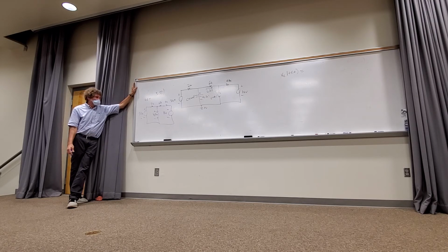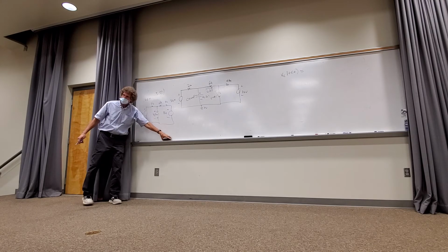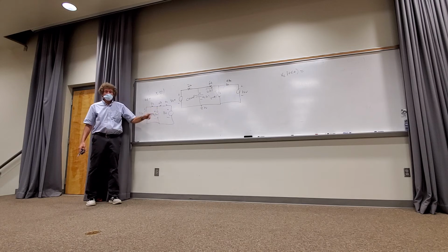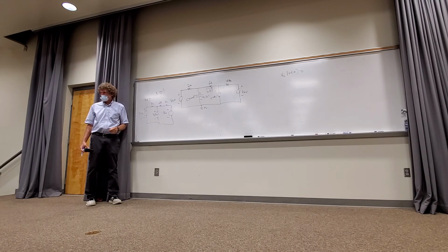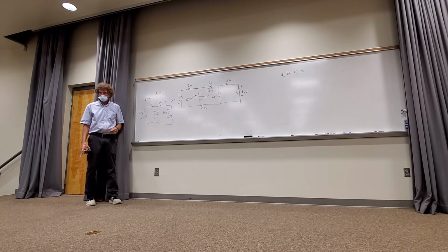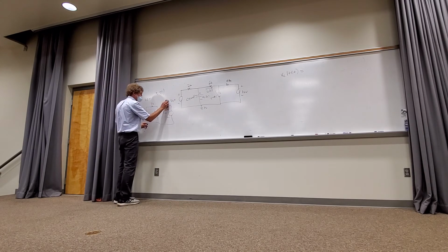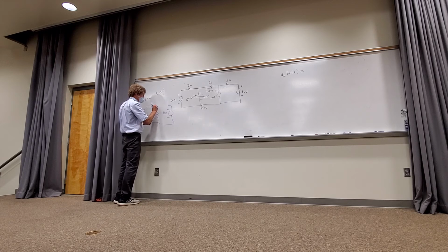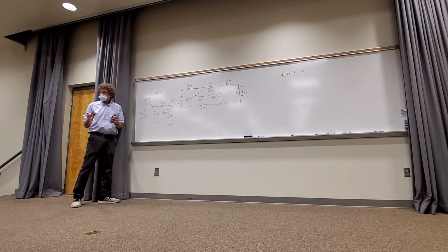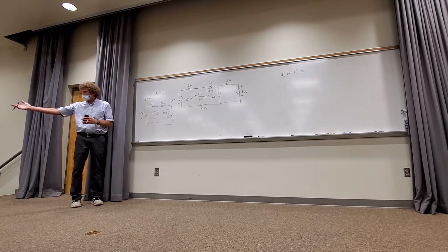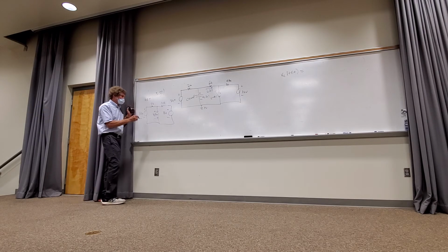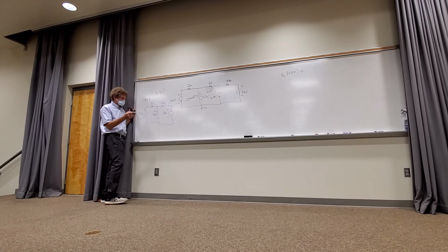All right, now I want this voltage. How you do it at this point is up to you. I would make one suggestion. This right here looks like a single resistor to me. You agree with that? So I'm just going to combine the 6 and 4 and make it 10K. Now, you may want to just get the current, so why don't we do it that way for simplicity?